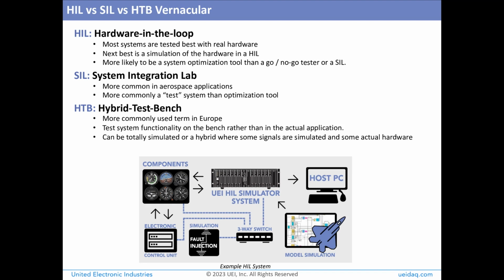A system integration lab, or SIL, has all the components in a system to be exercised and tested. Any that are not present can be simulated, as well as most of the signals from the sensors. I have heard the term cockpit on the ground. Many times this can include an actual fuselage so a pilot can, again, fly the system while on the ground.